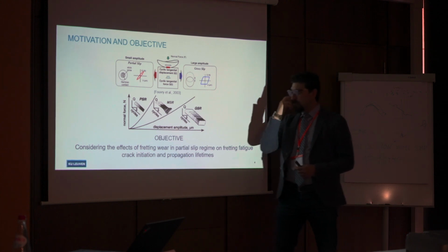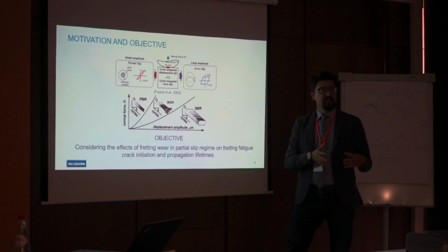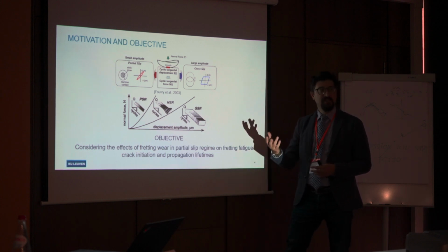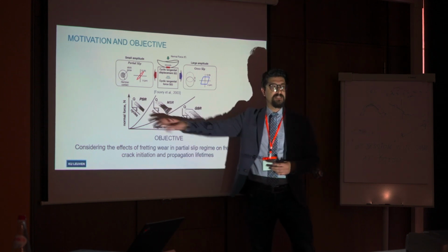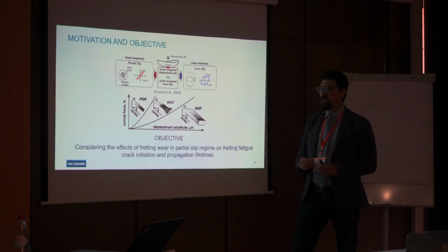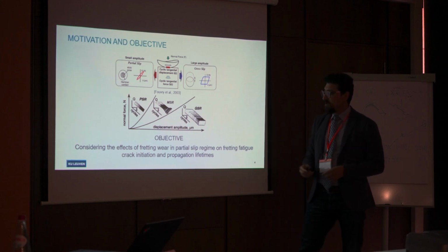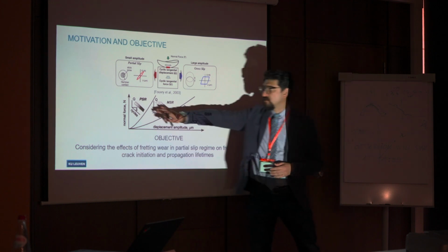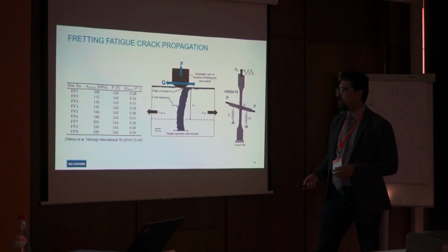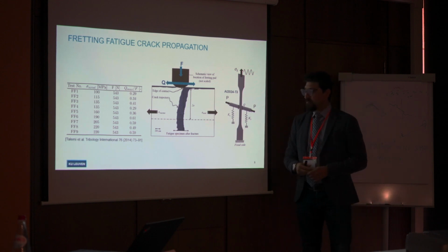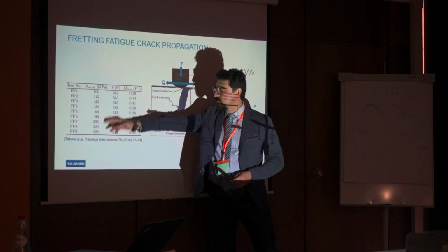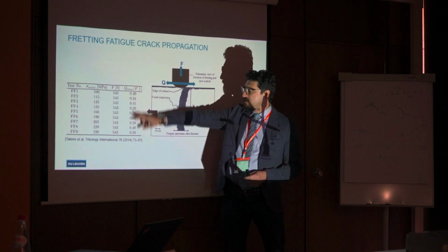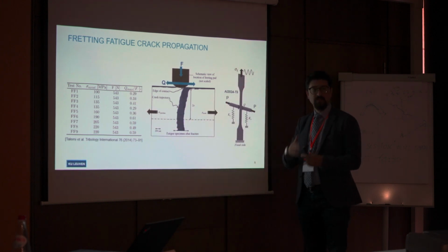But a lot of simulations try to predict fretting fatigue crack initiation and propagation without taking into account the local effect of the wear process. So what André did in his PhD, he tried to simulate the wear process plus the crack initiation plus the crack propagation, and monitor the effect of the wear process on crack initiation and crack propagation, under the partial slip regime. We used some experimental data which we performed a couple of years ago, so you see 9 experimental data points here. The axial stress and the normal force were constant, and then there is a ratio between the tangential load and the normal load.